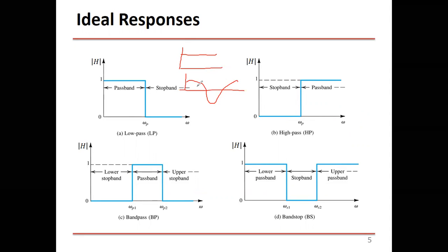You need a phase shift here of plus 90 degrees and here minus 90 degrees in this band of frequency. So you design an all-pass filter to change the phase response, to affect the phase, not the gain. So this is the main application of an all-pass filter: I don't say filter the phase, but to change or alter the phase of the signal at certain frequencies, different than the phase at other frequencies.